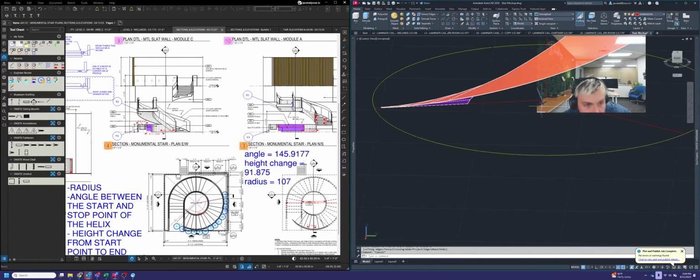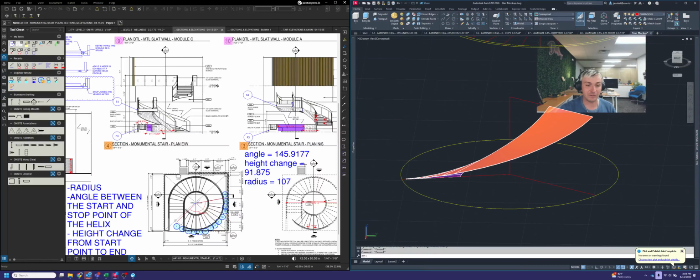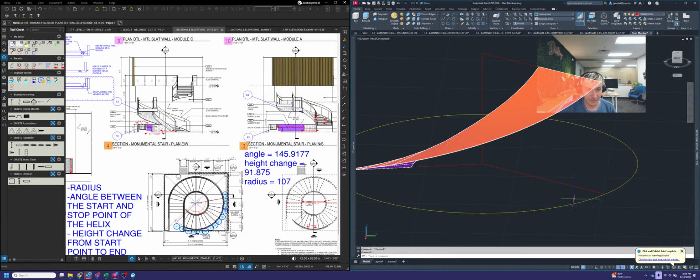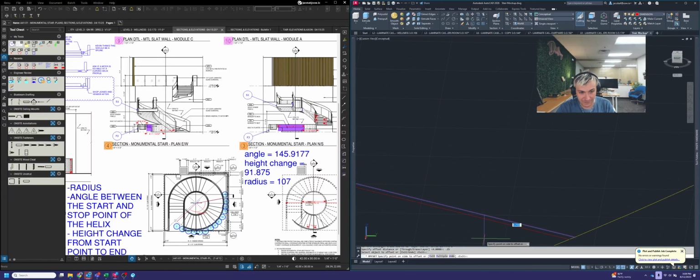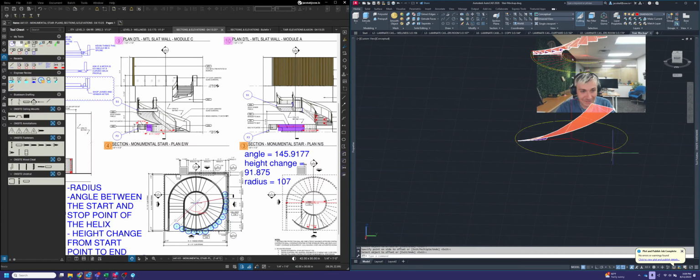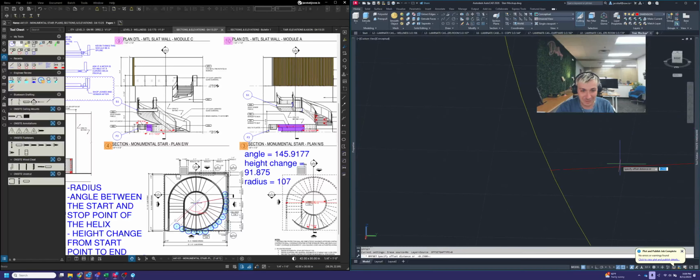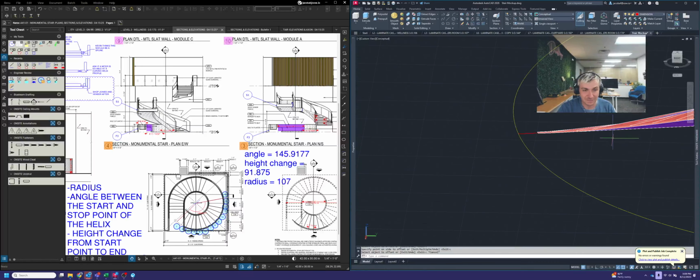Okay, so if you were doing this in the sense that, hey, I know I'm going to be doing a 1/4 inch spline reveal, you would still want to do what we always do, where you offset the endpoint a 1/4 inch off the path, so 0.25 this direction. Make sure that's right. It's so hard to tell sometimes unless you zoom in. And then same deal here, 0.25 out in this direction here.